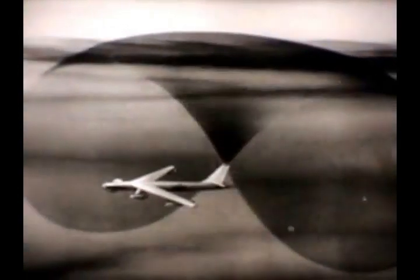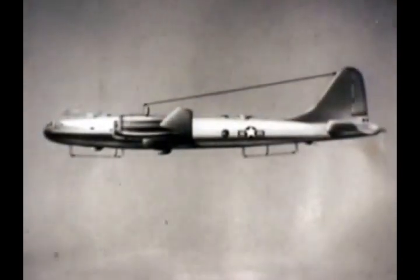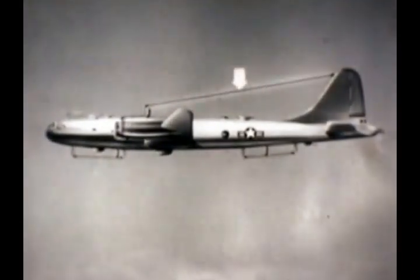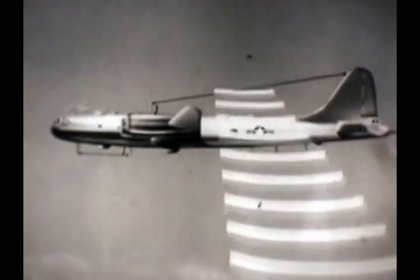Generally, it is located between the wing and tail assemblies and is shaped like an inverted miniature bathtub. The receptacle acts as a reflector, concentrating a greater amount of energy toward the antenna rod. The reception pattern is still like a teardrop, but more directive, sharper than the old-time outside-underside wire. Now, as you recall, while the command radio is basic for all aircraft, the liaison radio is also basic, but only for aircraft having a radio operator. A fixed wire extends generally from the stub mast to the vertical stabilizer. Its job is of course twofold: sending and receiving.